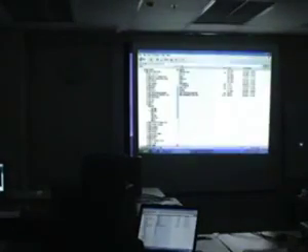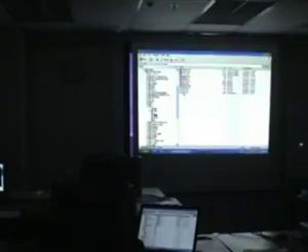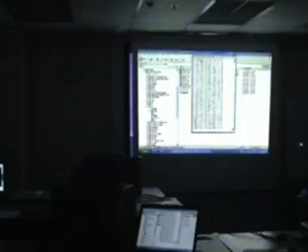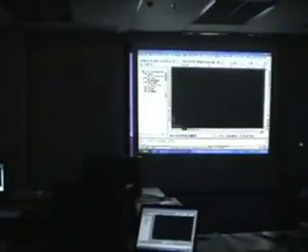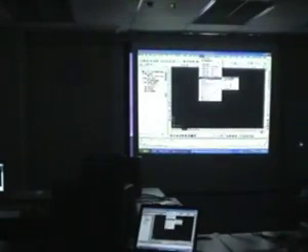So now we've got a report file. I'm just going to go to Windows Explorer to show you the file which has been created, points.txt. You can see this is what it looks like. We've got our X column, our Y column, and this is the string column. This is for Land Desktop also. Yes, Land Desktop also. So when we import this, we just go to Points, Import Points.